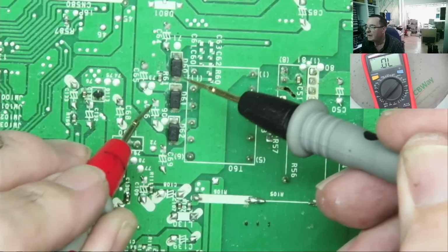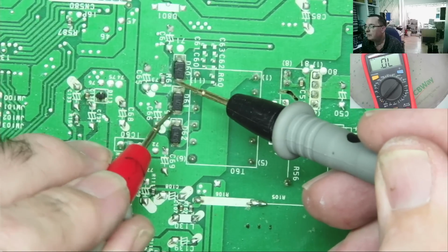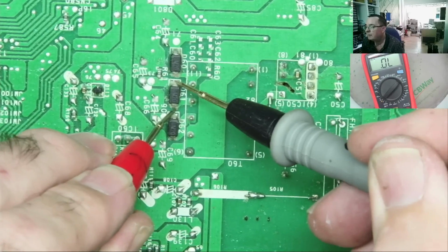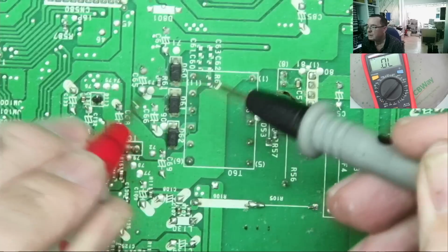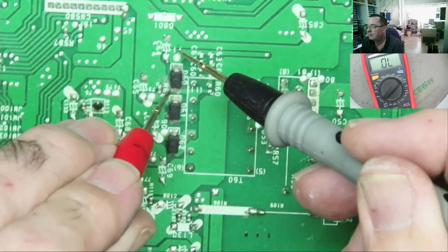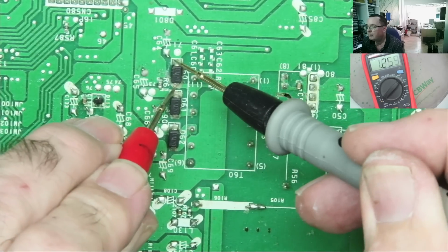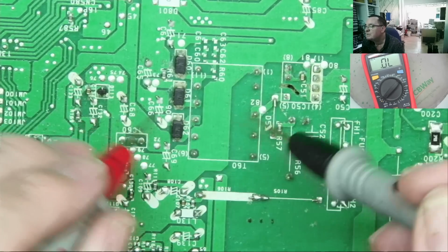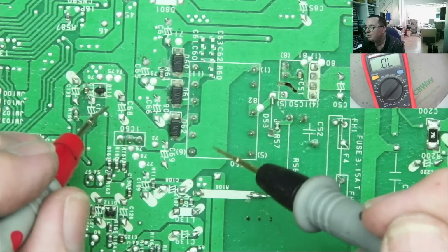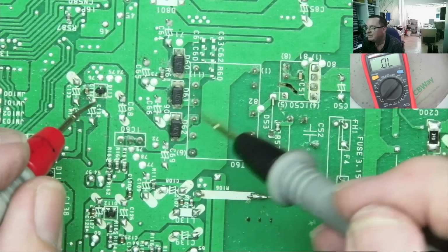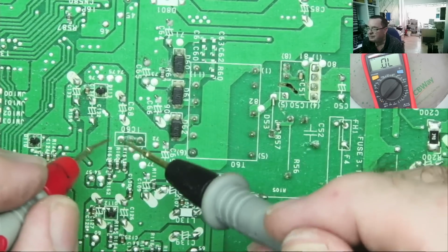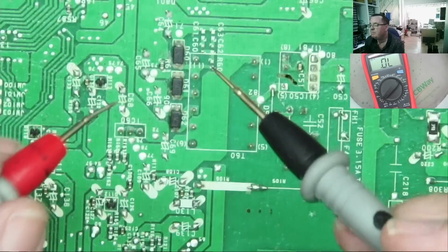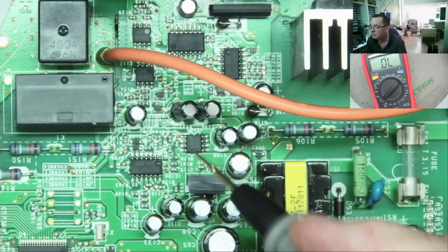That reads okay. That reads okay. That reads okay. Yeah, so they all come from the same transformer, so I think we can say if the 5 volts is there, these will be there as well, but we can measure them on the op amps. So on second thoughts, I don't think we need to look up the data sheet of these right now.